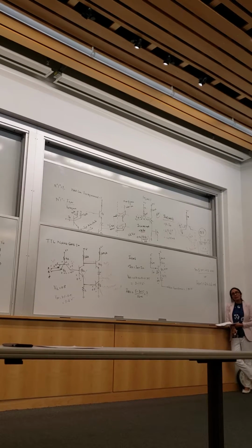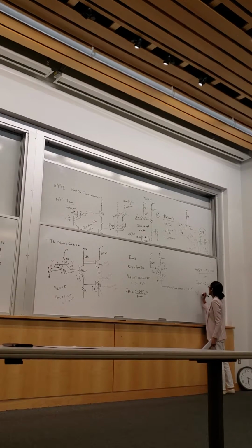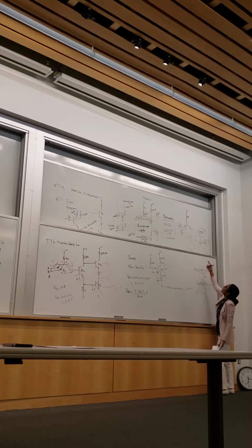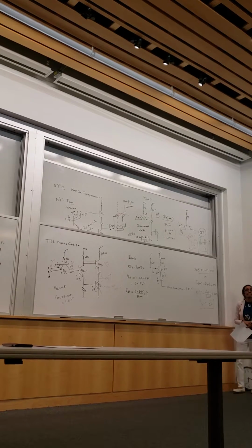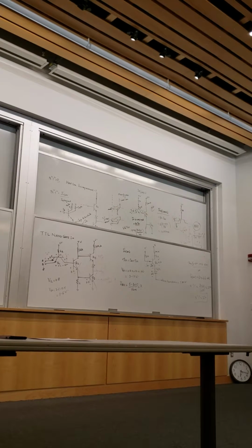Good. Now you have I not available. You have the worst case input high requirement. So your fan out for logic high would be 24.66 divided by 1.075, right? That's gonna be 22.93, and we always take the lower value, that's 22. Now you should be able to solve it for logic low at the output. Good?